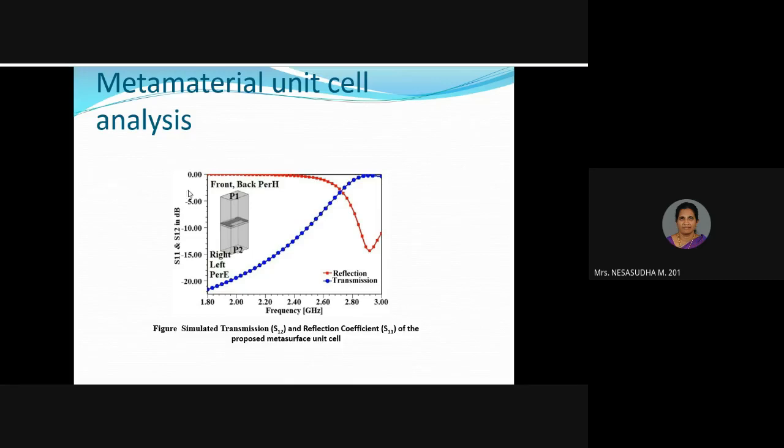When you measure the radiation at the same place as port 1, it is called S11. Whatever you send at port 1 and how much is returned back is measured in S11. That is called the reflection. So how much radiation is reflected back is measured from the same port, S11. And then, transmitting at port 1, how much is radiated at port 2 is measured in S21.